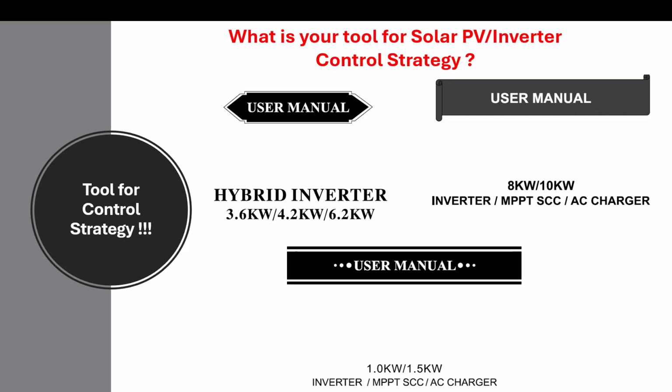You can ask questions. What have you set this? I want this. What have you put here? So that you also understand the boundaries of your system. Because sometimes there are certain inverters that will say they cannot support inductive loads, for example. This is written in a user manual.